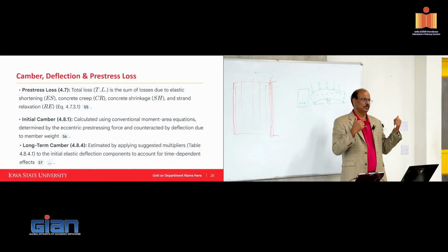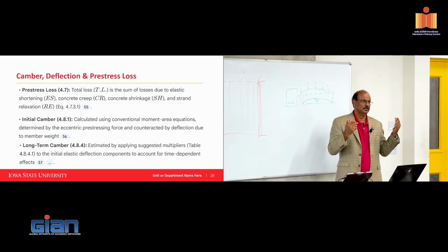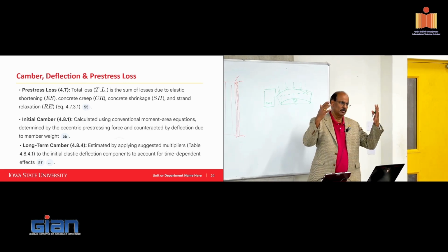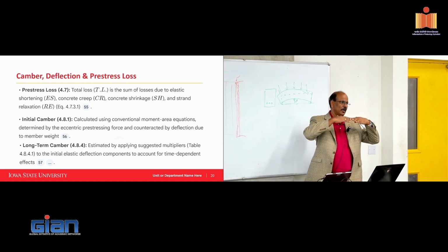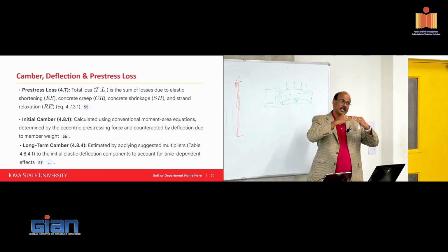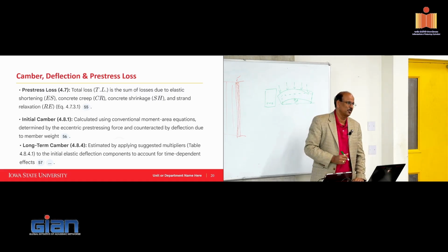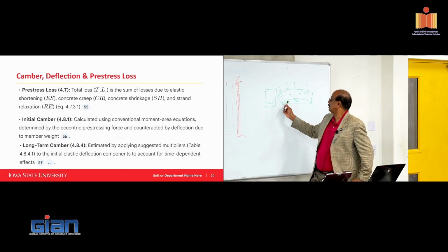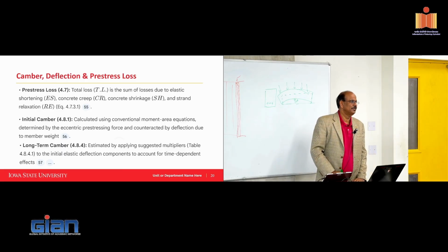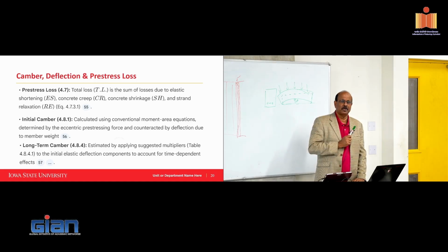Right? That's possible. Yes? Because if I'm starting flat and put a load, it's going to deflect downwards. But if I start with a camber and put a load, it can stay with an upward deflection, it can be flat or it can go down. All three are possible, depending on the amount of prestressing you put in. But my question is, what's the advantage if I keep it flat? What stresses do you think are in the beam if I keep it flat?